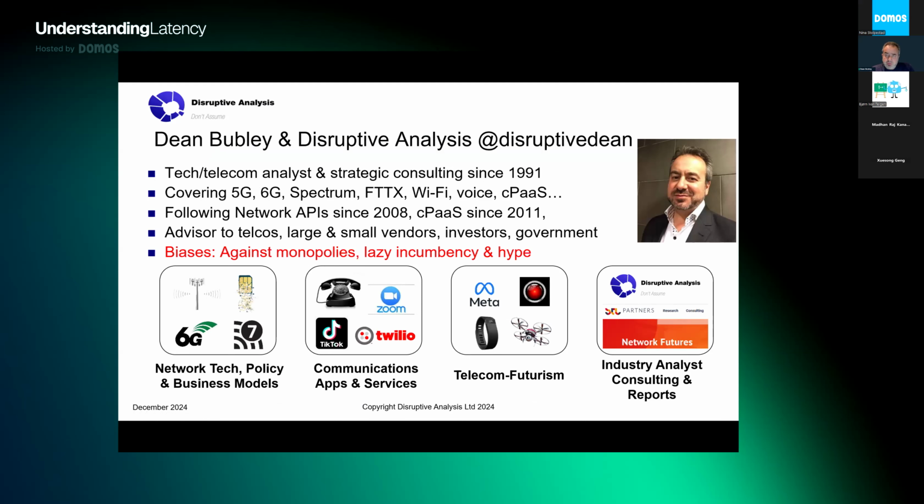So this is just an example where I was sitting right by the window in a new part of London in King's Cross. As you can see, 2 meters from the window, and I had no signal at all. Simply because essentially the foil in the window for insulation purposes blocks out certain frequencies of wireless, and that's going to get worse as we get better insulated buildings, whether it's windows or walls, over the next 10 years or so, with moves to more sustainable construction as well, because the construction industry is more interested in the thermal characteristics than the wireless ones.